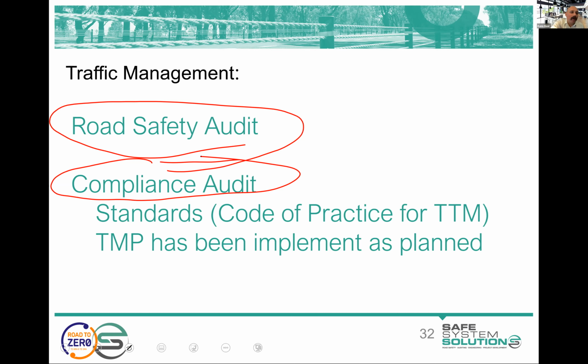There's also a bit of compliance auditing, which is what I say your surveillance officer or site engineer might do, which is to check that whatever traffic management plan or traffic guidance scheme was produced has been laid out as per what was required, and checking that it's maintained, that things haven't been knocked over, and so checking the taper lengths, the right bollards are out.